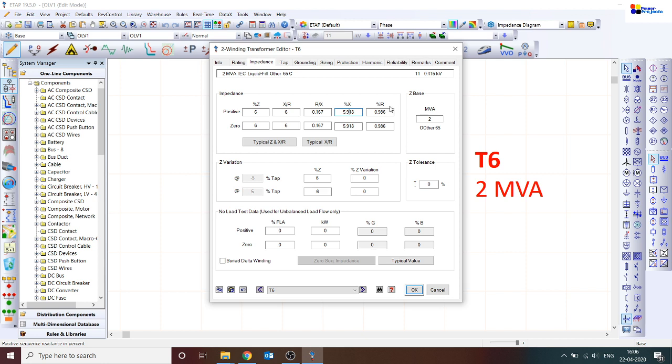Current tends to concentrate more on the outer surface and less on the center. So when the current flows higher at the outer surface and lesser at the center, the losses created in an AC line and a DC line for the same current flow will not remain the same. The current is not uniformly flowing, so there will be increased losses in the AC network. I am not talking about the reactance or capacitance, I am purely talking about the resistance.